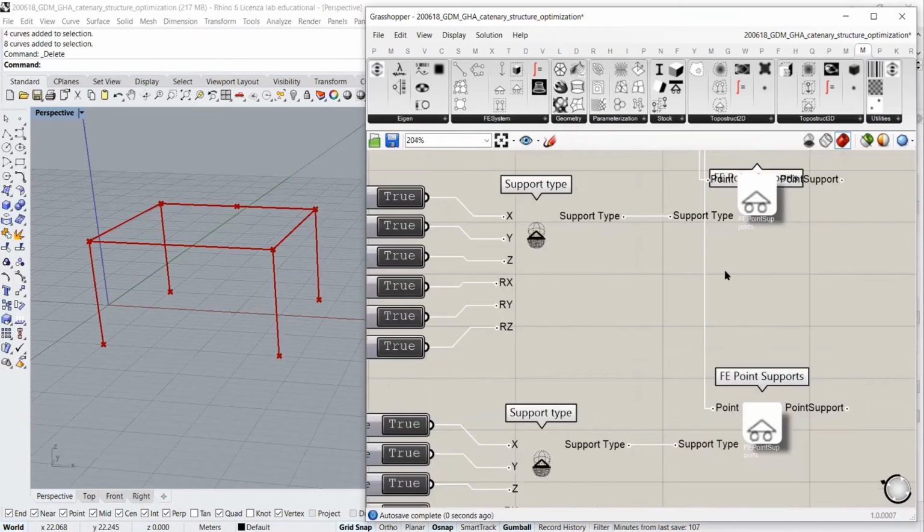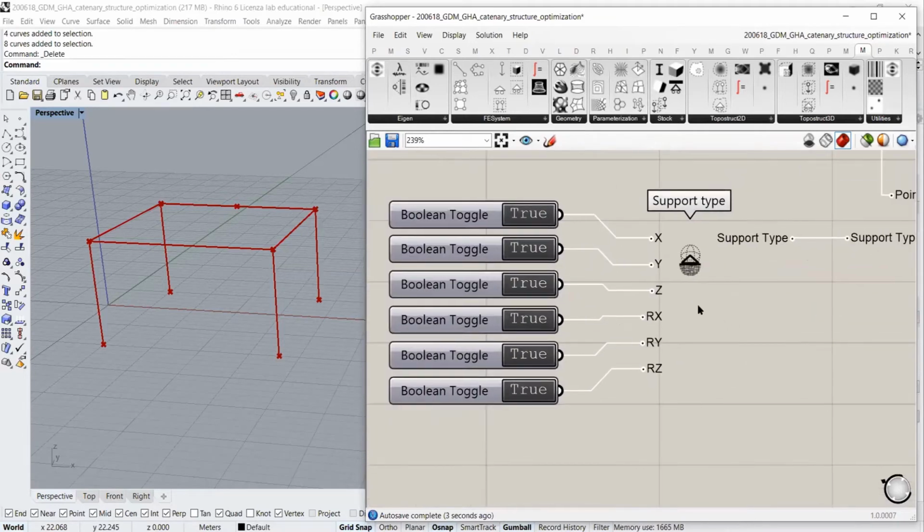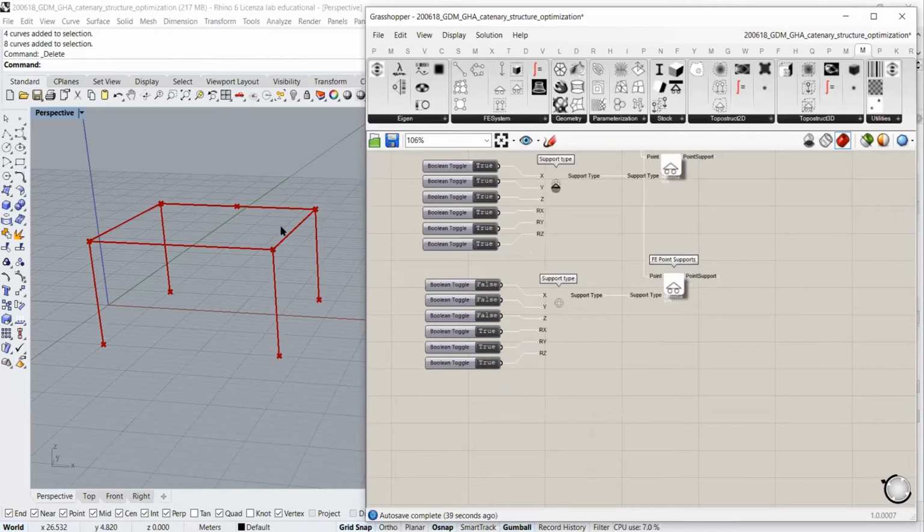And in this case, what I want is to avoid rotation and allow translations. Okay, so this is what I'm going to do here. So this structure can deform freely because these points are not connected to any physical constraint. Okay, they can move because the structure can move, but what they avoid is the relative rotation between the beam and the column, the beam and the beam, and the other beam and the column. So this is a rigid joint, basically, but it can move in space in 3 directions. So I think that's pretty much it.